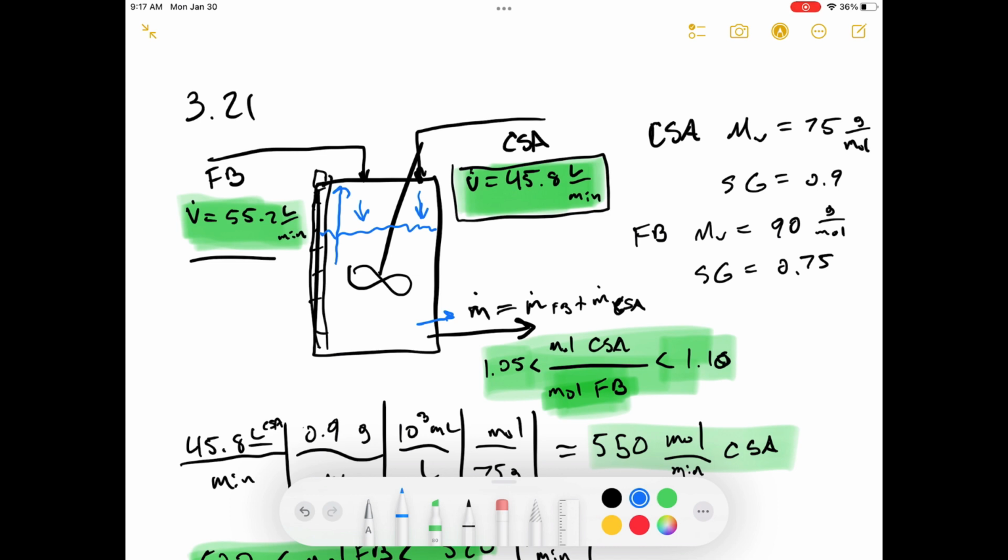What would happen is that if you have the ratios off, the reactor would form a solid plug. So this solid plug might get so full that it blocks the mass flow rate coming out. So the mass flow rate would reduce coming out, and so you would start having a rising level in the tank.